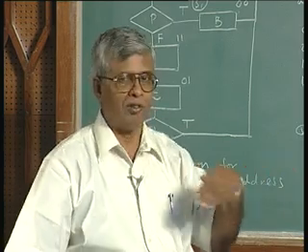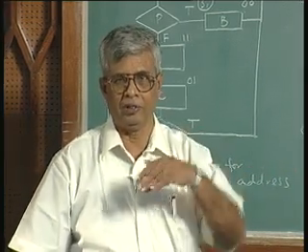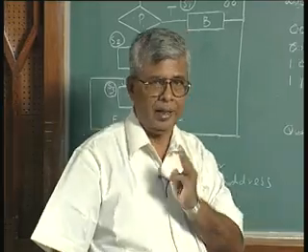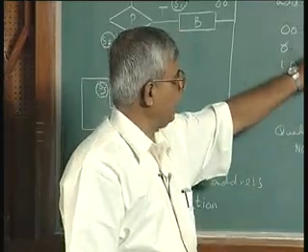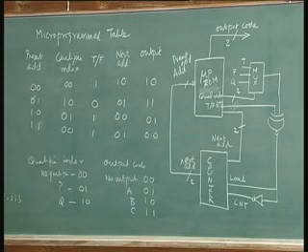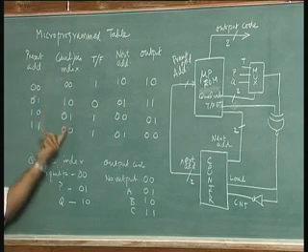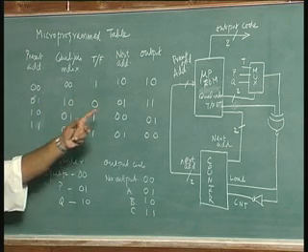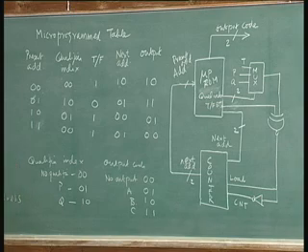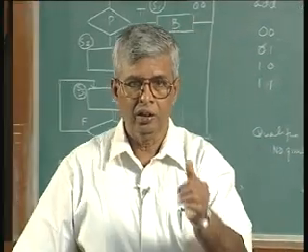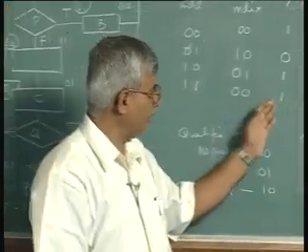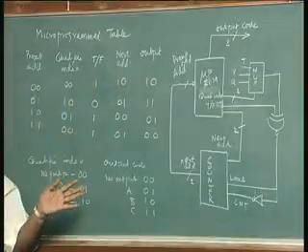Supposing we had 5 qualifiers instead of 6 qualifiers, earlier were 5 qualifiers, 5 qualifiers would have required 3 bits. Now, an extra qualifier index being 0 0 0 will not add any more bits. So, the number of bits increase is not there. 1 extra bit will be there for true false bit, but if the next address is several bits long, I will increase 1 bit for true false bit, but save on 1 address.